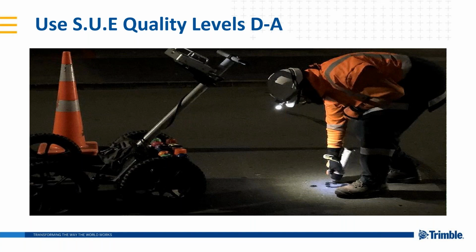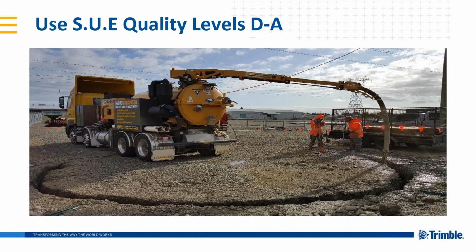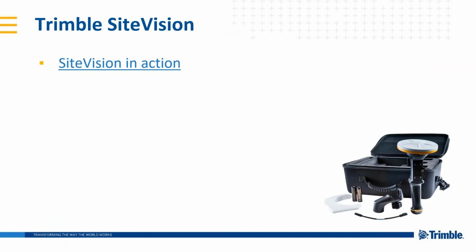And you would have seen streets and footpaths covered in little spray paint diagrams of where asset layers are actually being located. Or you can get to what's known as potholing, where we assume and mark out an asset underground, and the only way to truly identify that that's exactly where that layer is, is to do a small dig to locate that service. And hopefully it's only a small dig and not requiring an extensive level of mining to locate the actual asset. And that would be the highest quality.